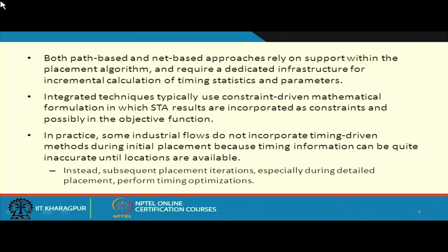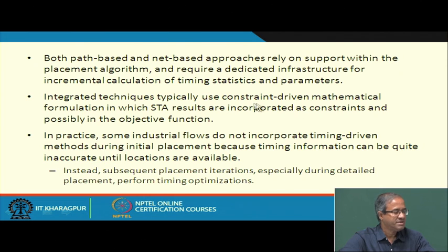In contrast, the integrated approaches, the third approach that we have also considered, use some kind of mathematical formulation. They formulate some constraints. In these constraints, the static timing analysis can be built in, some results of STA, and there is some objective function defined which we are trying to optimize.